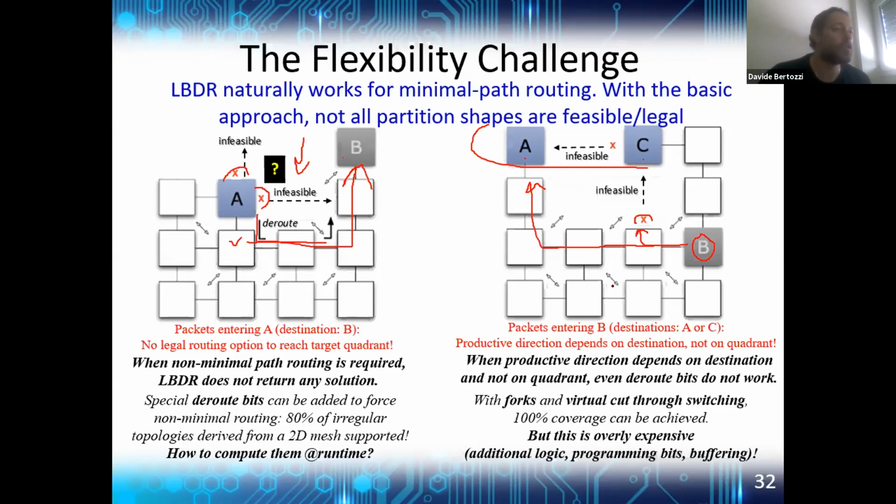But again, there are solutions to work around these limitations. For instance, you may think of duplicating the packet here. In B, you create two replicas of the same packet. You do a fork. Then, if the destination is A, one replica will reach the destination, and the other replica will simply stop here. When the LBDR logic bails out, you simply discard the replica.